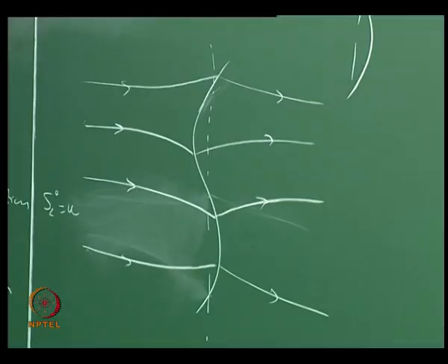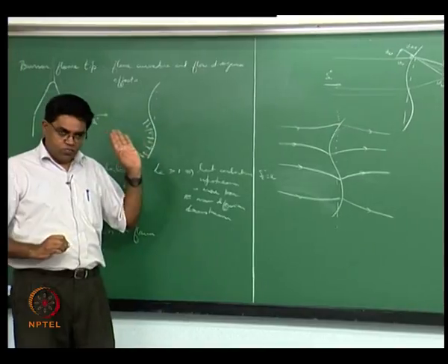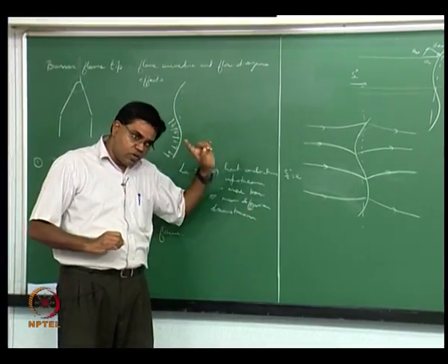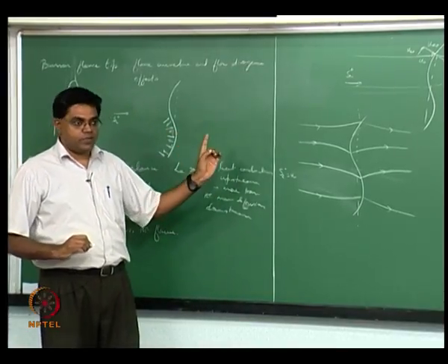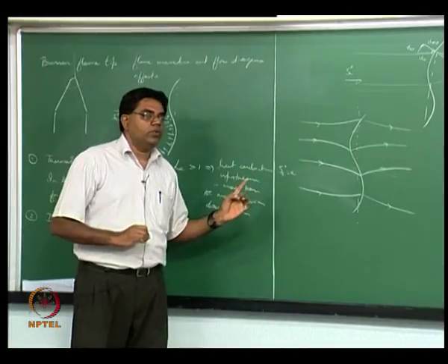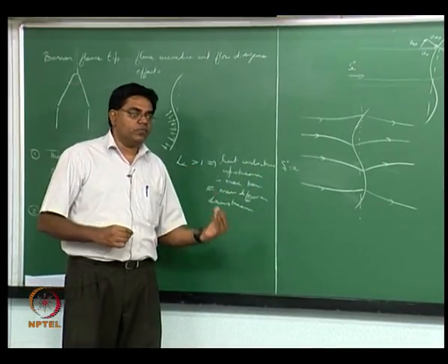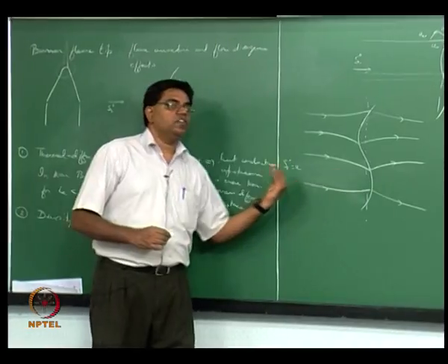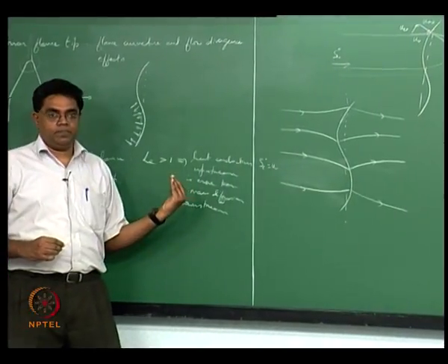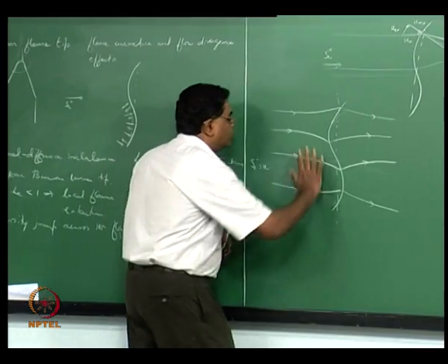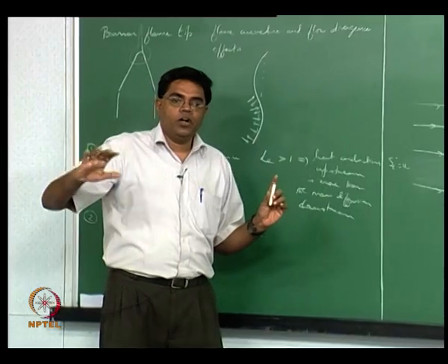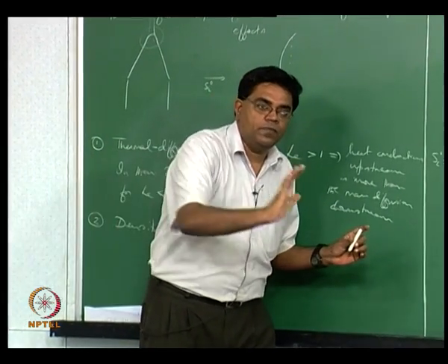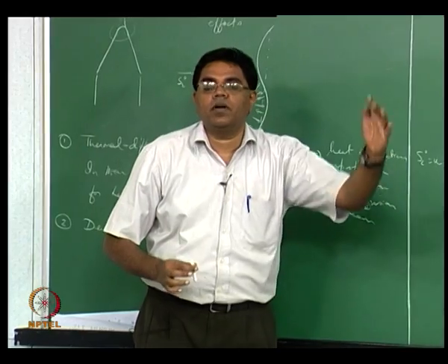This is very important, I think I mentioned this earlier: the way we always want to think about a flame propagation speed, and I will reiterate this when we deal with triple flames after diffusion flames, is always relative to the flow speed far upstream of the flame. You don't want to worry about all this mess; it all boils down to how much I have to open the valves for my flow to set in so that the flame is approximately stabilized.